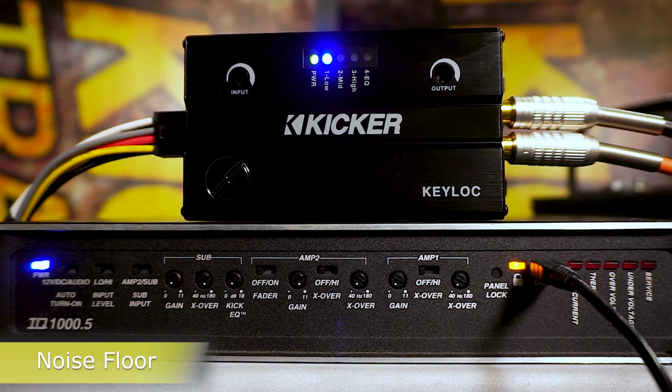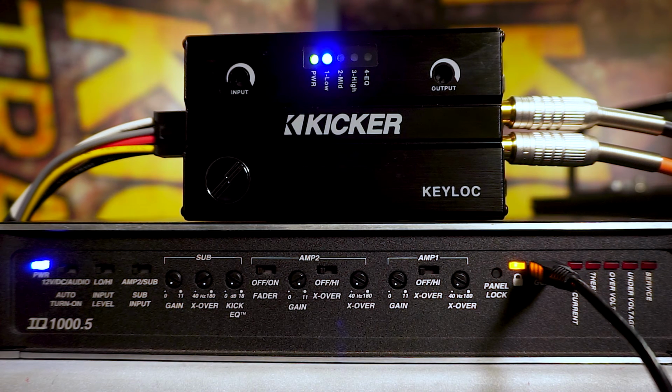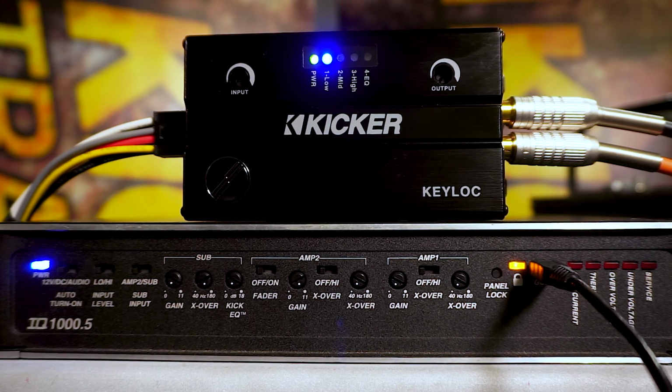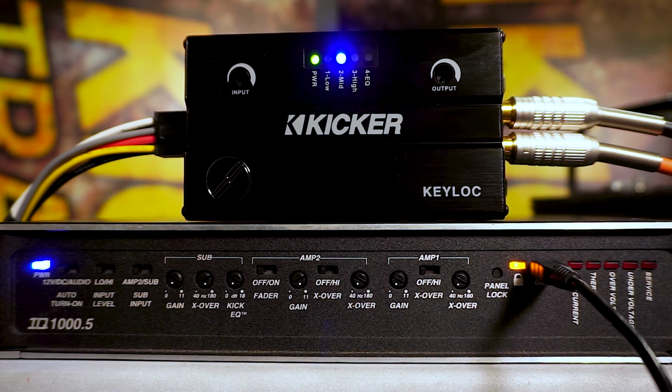Play the noise floor track on your source unit with the volume still remaining at 3/4 output. Make sure the noise floor track is playing before you begin the next process. You will simply press the key button one time and you'll notice the number 1 LED will begin to flash. That tells me it's detecting the noise floor in your system. Once the LED 2 begins to flash, now you're ready for the next step. Immediately press the next track, which is going to be full test.